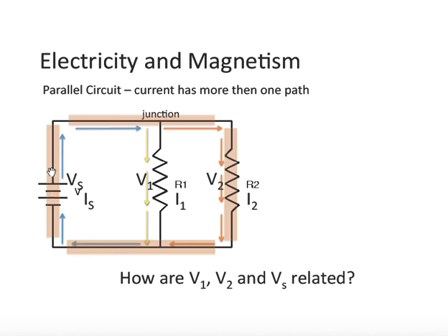I'm going to go around one more time. So at the source, we write Vs. Now we're going around, and we're going to hit this load, which is V2. And that's the only other load we're going to hit. Here, the electrons gain energy. Here, the electrons transfer their energy to the load. That's why we're writing Vs equals V2.